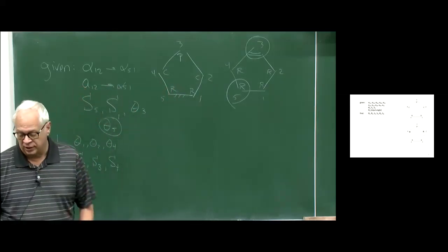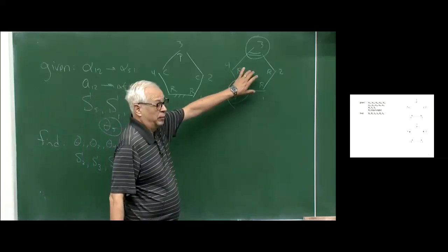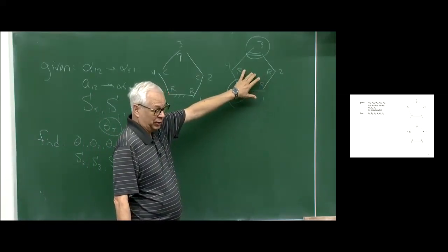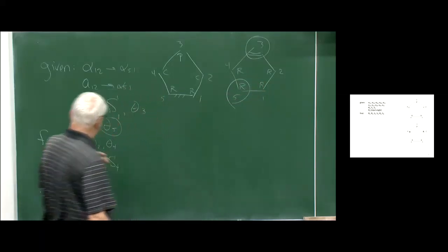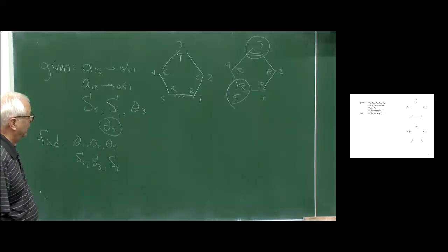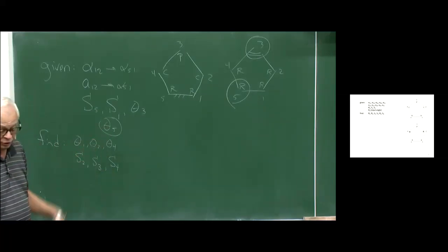So it turns out that the reason these are going to be so easy is because the equivalent spherical mechanism is 1 degree of freedom. We're going to be able to solve that based on what we did in chapter 6. We're going to get an A and a B case. We're going to be able to get all the angles. So we're going to get theta 1, 2, and 4 A case, theta 1, 2, 4 B case. And then we do have to learn how we get these values, but that's the new part in this chapter.